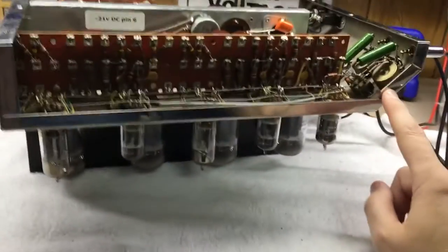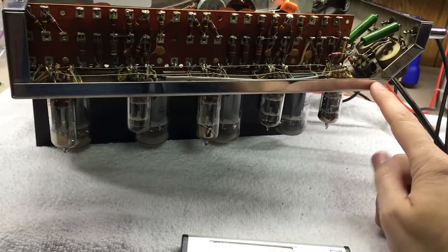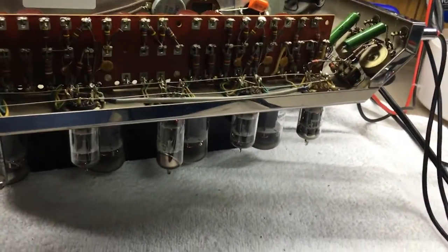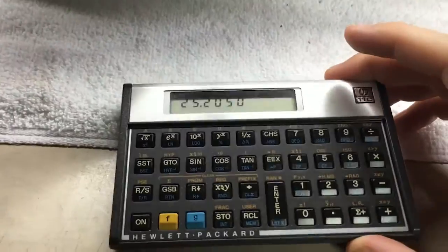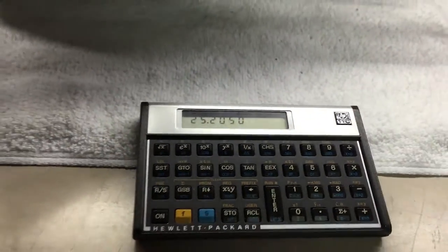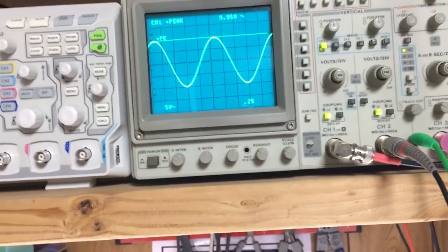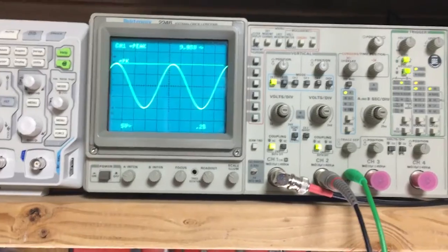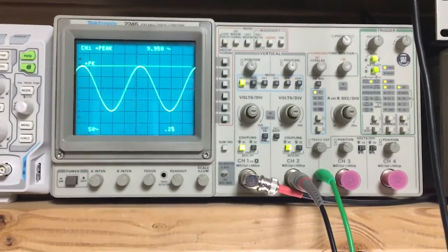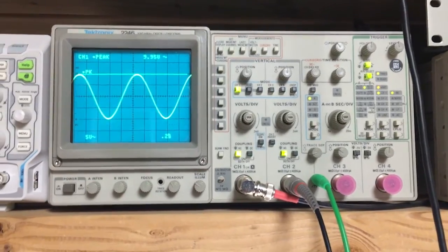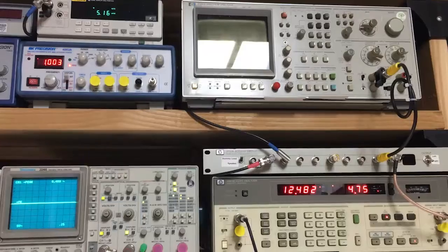Well, this is a Macintosh 225 amplifier right here. The 25 in the 225 stands for it being a 25 watt amplifier. So it would make sense that at 25.2 watts, it's starting to clip. So that's just another thing you can use the power output or the voltage measurement for, to determine maximum power output before an amplifier starts causing distortion. I'll jump you over and show you one more thing.